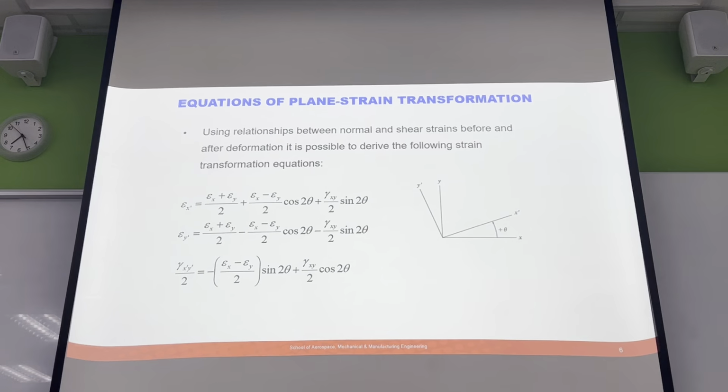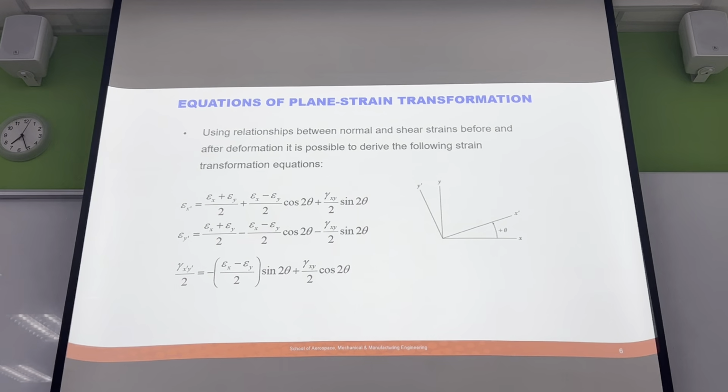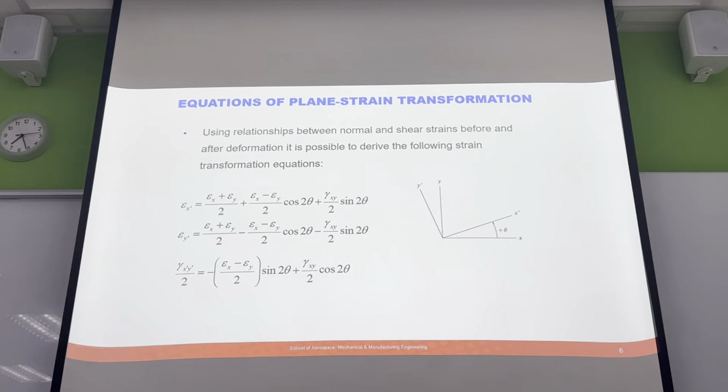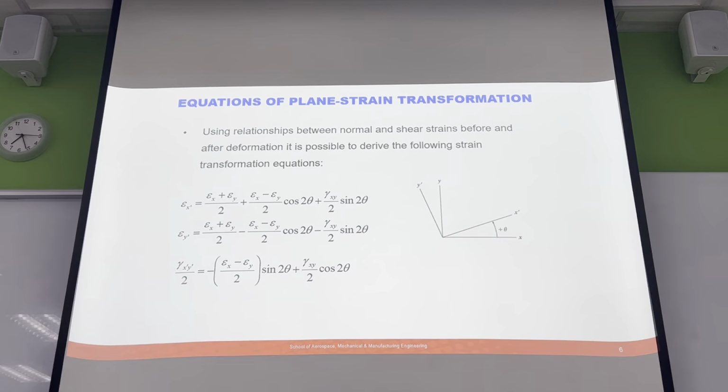We measured the strain on a system, and the direction we measured it in wasn't actually the direction we were interested in, because we couldn't lay the gauges for various reasons. Sometimes you can't lay them in the directions you want, right? And so then we're more likely to use these strain relationships, because that's actually what you can measure. And then at the end of it, we can convert that back into stresses. But you can measure strains directly, which is why these are used.